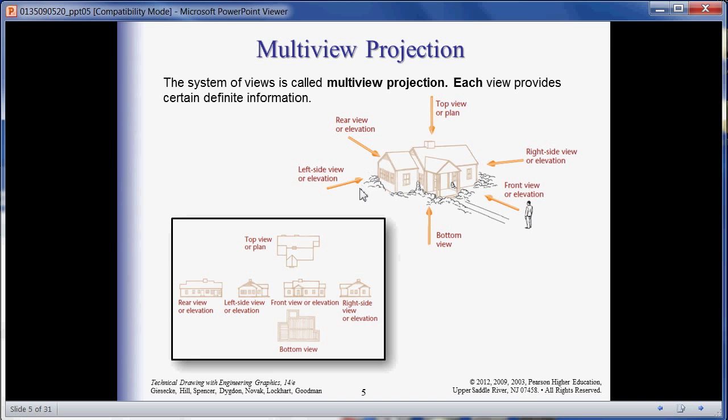And in the architectural case, we have six primary views as well. We have the front and the elevations. We call these in the mechanical world the side views, but in architecture they're the elevations, and often in civil engineering we call them elevations as well. But look at this reference picture right here. Notice the front, top, bottom. We would never see the bottom on an architectural building. We would see the right side and the left side, and then the rear back here.